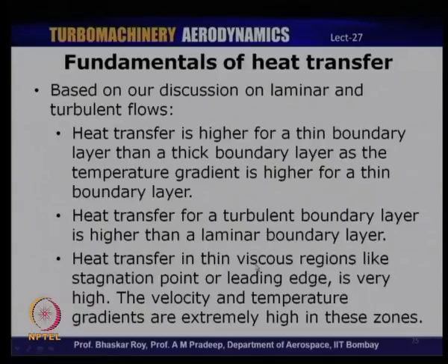And heat transfer in the thin viscous regions near the stagnation point or leading edge is very high. In these regions the velocity and temperature gradients are extremely high, and that results in extremely high levels of heat transfer, especially in the regions close to the stagnation point, and that explains why we have seen the high level of heat transfer taking place close to the stagnation point.